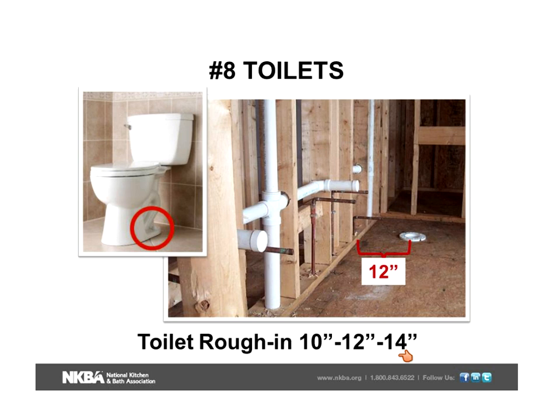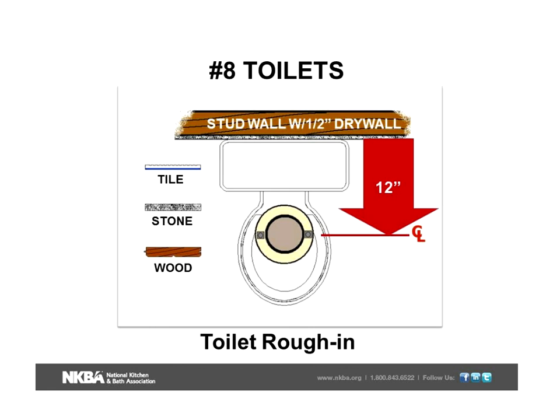So you can figure that if it's like 11 and a half, you've got a 12-inch rough end, unless something really funny is going on in that wall. But again, this is one of the things that you want to measure before you order the toilet. Now, it's very possible, and in some of the more popular toilets, the Cadet, American Standard, the Wellworth, Kohler, they do have 10 and 12 versions of this toilet. Same toilet, two different rough ends, so that'll save you. But when you get into some of the more expensive ones, if there is a set rough end, you better check it every time anyway.